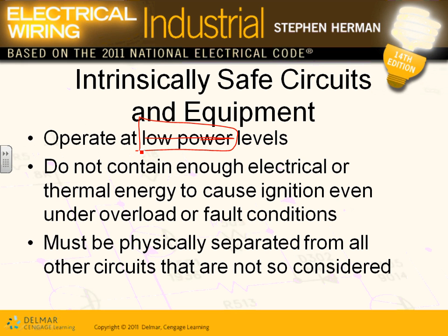So you classify it then. When you have this system, you can install it in class 1 div 1 locations or class 2 locations. You still have to seal when you put them in conduits. You have to seal when you move from one location to another. But that's easy. My understanding is they came up with this system, guys, to help you avoid doing a lot of hard, rigid wiring for a lot of locations.